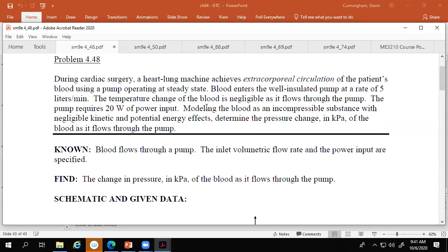Now, an air compressor, you see a gas, that's a whole other deal. 70–80% of the energy when you're compressing a gas goes into temperature increase and the rest goes into pressure. But because this fluid is almost incompressible, we'll probably assume it's incompressible. It's not quite, but it almost is. Then there's not that opportunity for all that friction between the molecules to build all of that heat inside the gas.